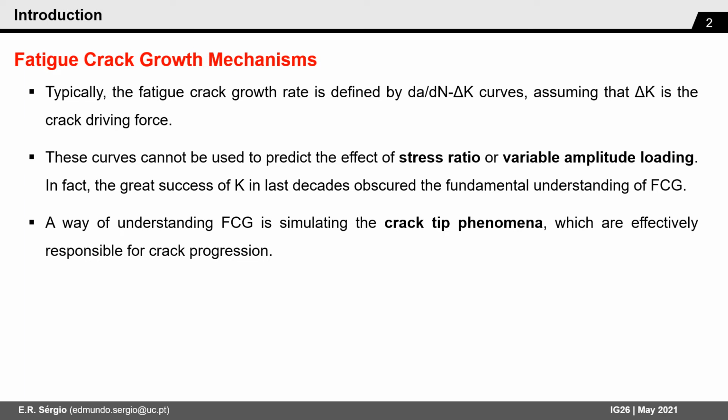However, this approach is not able to predict the effect of stress ratio and variable amplitude loading on the propagation of cracks. In fact, the great success of K has obscured the fundamental aspects of fatigue crack growth and its understanding. The true way to understand it has to be related to the mechanisms acting at the crack tip.